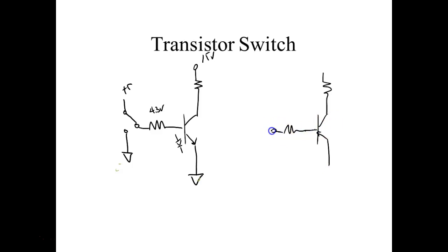But what I would be doing is switching this from a negative 5 volts common, and up here this would be a negative 15 volts. And that would be for a PNP, but the circuit would work the same. This would still drop 4.4 volts. This would still drop the difference between this and ground.